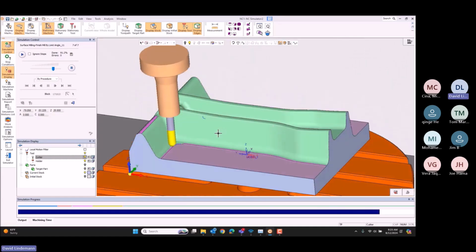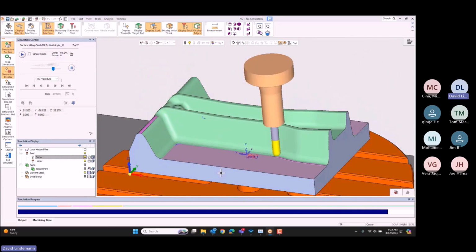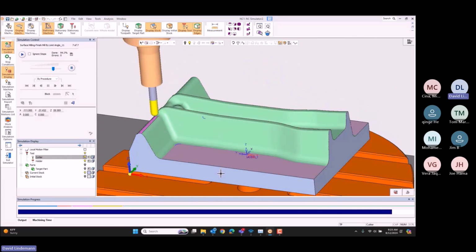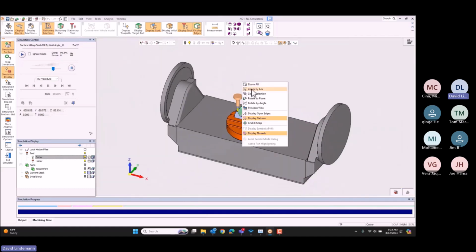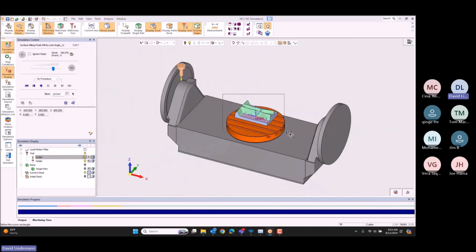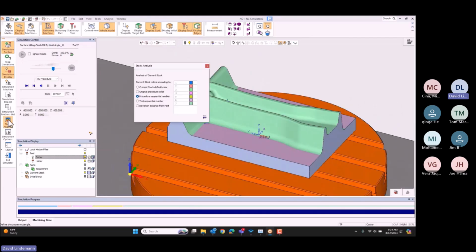A lot of people are using 5-axis now because the machines are cheaper, and it's more like a 3+2 that they're doing. They're doing 3-axis tool paths across different setups. Basically they rotate the part 90 degrees, or rotate the insert 90 degrees, cut it from the side, flip it over again, and cut it that way.